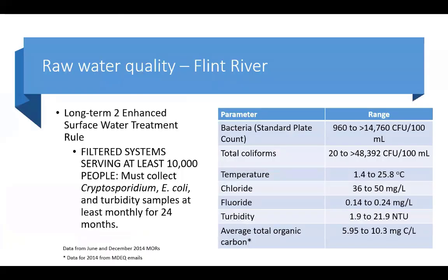Now, as part of the Long Term 2 Enhanced Surface Water Treatment Rule, filtered systems serving at least 10,000 people must collect samples for Cryptosporidium, E. coli, and turbidity for at least 24 months before distributing water. To my knowledge, that never happened.